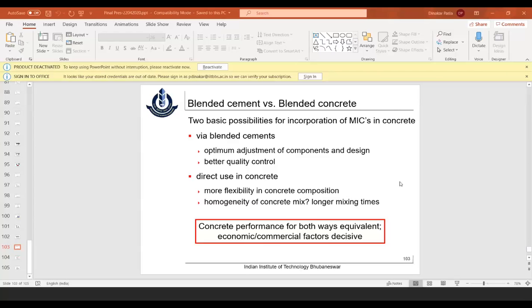Yes, it was. In fact, there were some questions also, like say in case of PPC cement or blended cement, should we delay the removal of formwork as compared to a concrete made with OPC? I think it is more to do with concrete strength rather than with the type of cement. If you are able to get a concrete which gains strength quickly, I think you can go in for the removal of shuttering and all that.